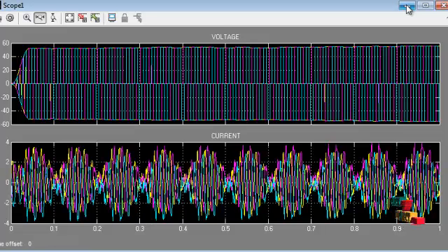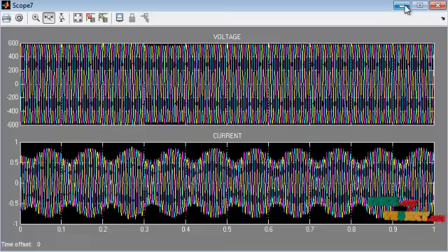The inverter converts the DC to AC, and that voltage is multilevel. Next is the output grid voltage and current waveform, and those waveforms are zoomed. The topmost waveform is the voltage waveform, and the lower waveform is the current waveform. So overall, load circuits will be disconnected using the circuit breaker and relay conditions in the function files. Overall efficiency will be increased by the controlling parameters used in the space vector pulse width modulation in the inverter circuit, and also the sliding mode controller used in the DC to DC conversion.